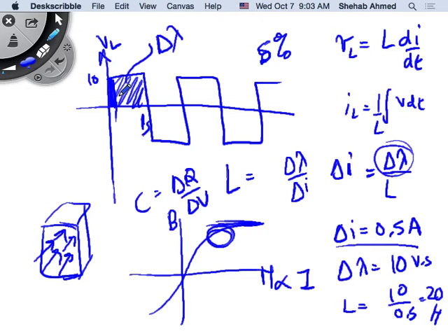But when you're operating at very low frequencies, like for these simple power rectifiers, when you calculate in your homework, you will get hundreds or thousands of microfarads. He wants to use picofarads and nanofarads in the same power rating for a converter. He can do that because of the switching frequency. I hope it's clear. Is it clear now how the L's and C's will differ?